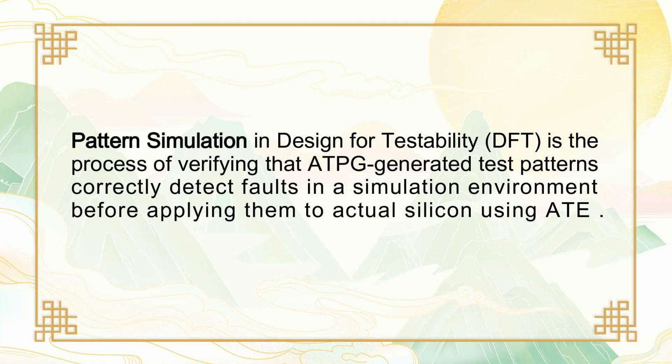Pattern simulation in design for testability is the process of verifying that ATPG generated test patterns correctly detect faults in a simulation environment before applying them to actual silicon using ATE. It ensures that test patterns work correctly in simulation, they meet timing and DFT constraints, they detect faults effectively, and false failures on real hardware are avoided.